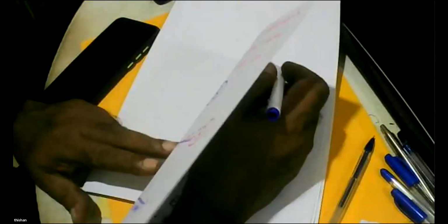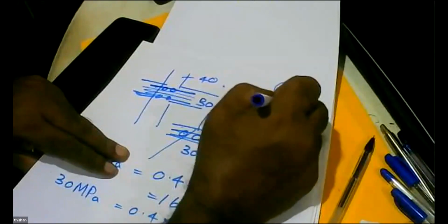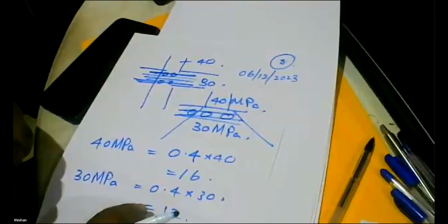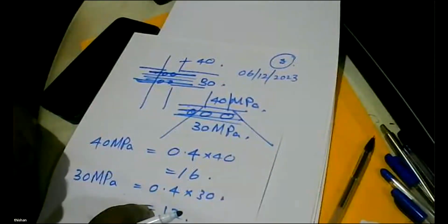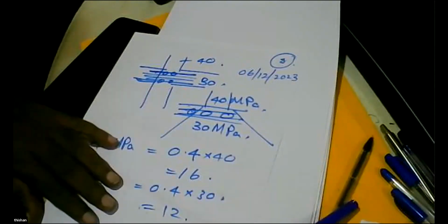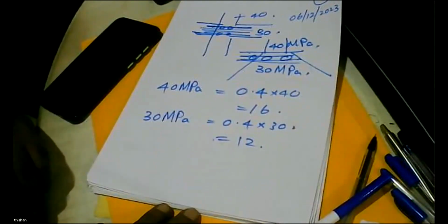So you have to get fly ash that has passed the tests. If you ask a cement manufacturer, they buy only fly ash that passes the carbon test. If there is too much carbon, then it is an impurity. So you have to get the specification for class F fly ash and check whether the product that you buy satisfies that. But the moment many construction companies are buying fly ash, it will become readily available, high quality fly ash. Is that clear? Yeah, thank you, sir.